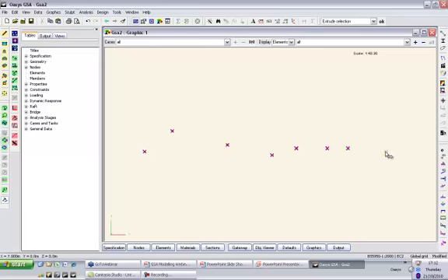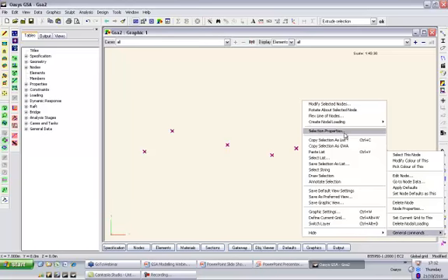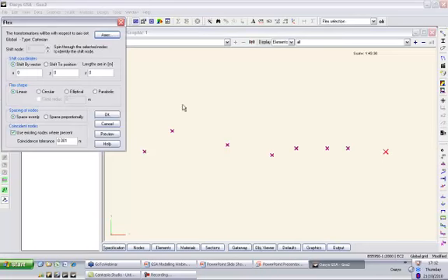If we want to even these up, there's a wonderful thing called the flex command. If we just straighten up linear, straight line, space them evenly, it just straightens them all up. Alternatively, space proportionally, which might be a useful exercise depending on the structure.